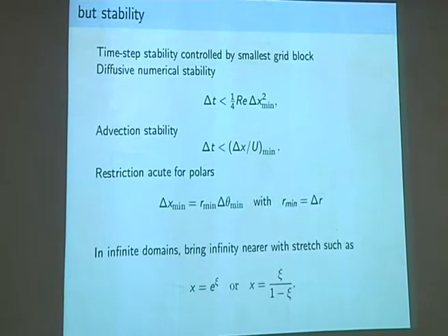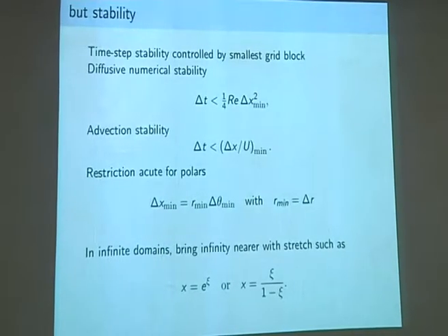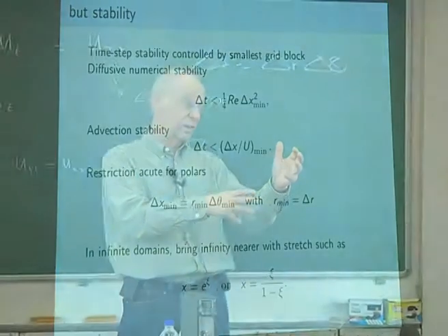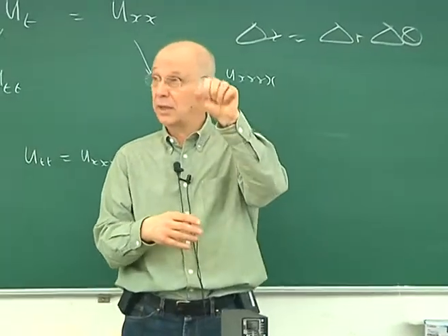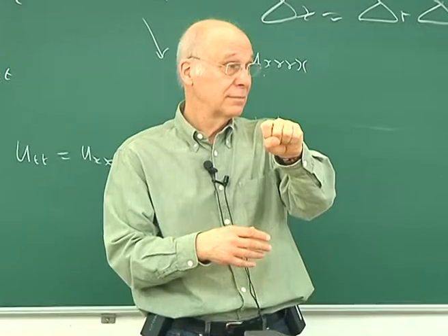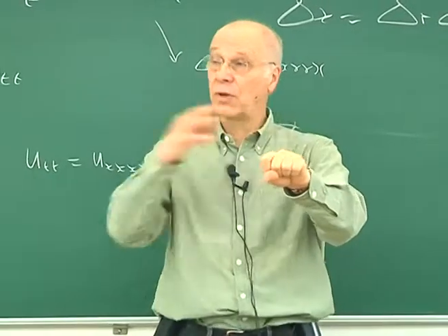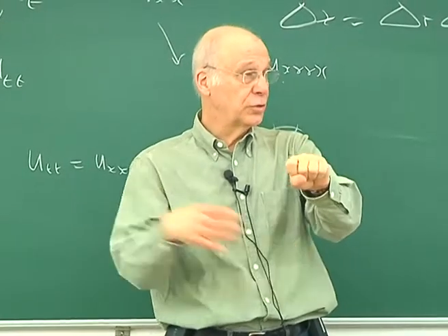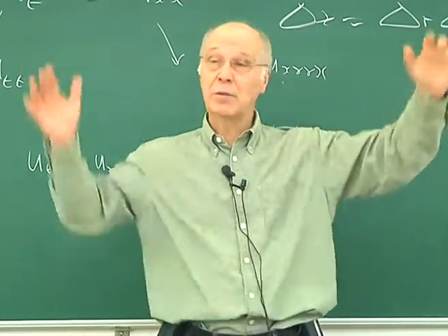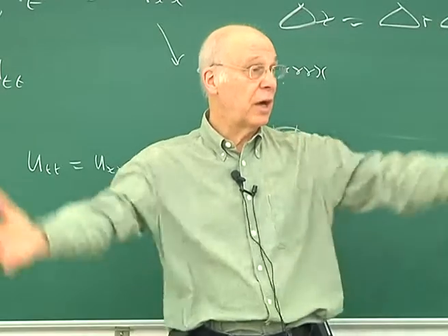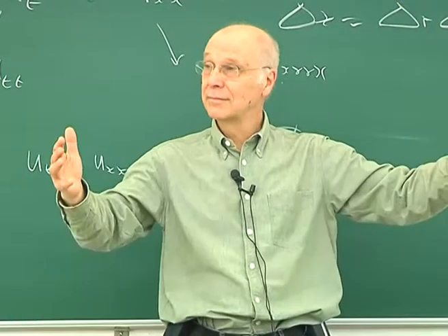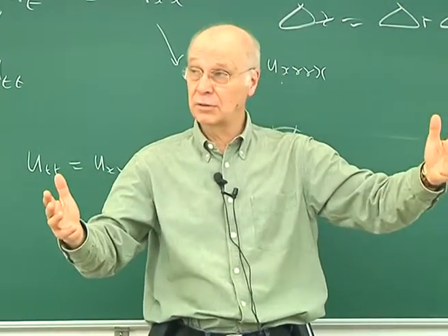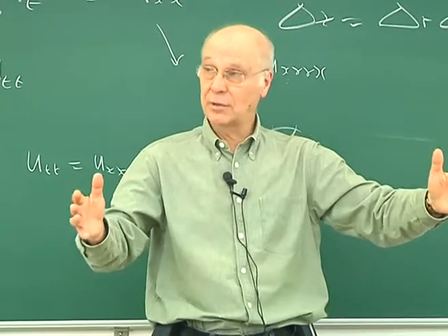There are actually much better things to do, which is to understand a bit of physics. If you understand the physics, what is happening in the far field for flow past a sphere is you are seeing a point force, the drag, in a uniform flow. We can look up Oseen's solution for a point force in a uniform flow, and then we can apply that at x equals 5. There's an unknown coefficient because we don't know the drag. We're trying to calculate the drag.